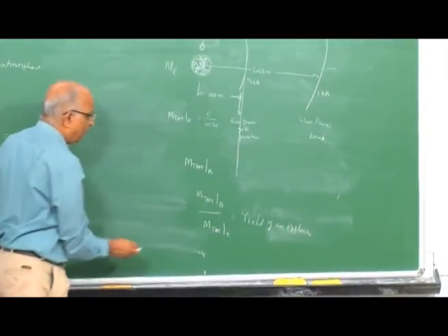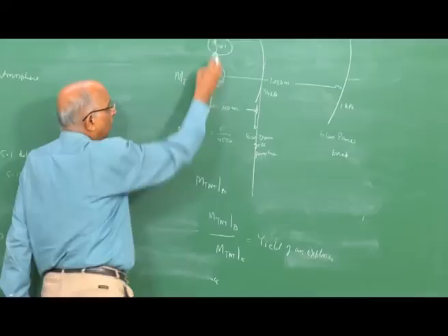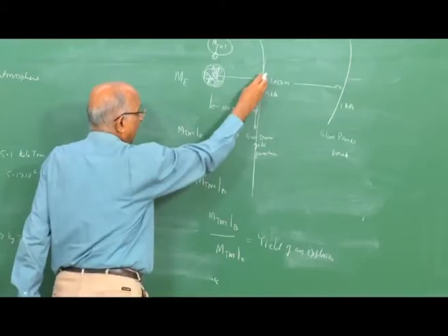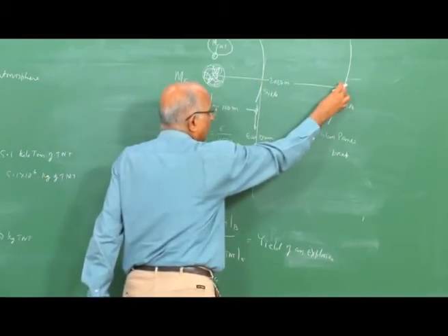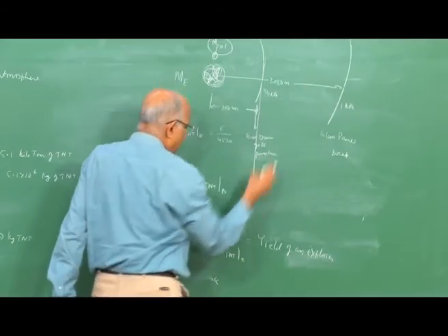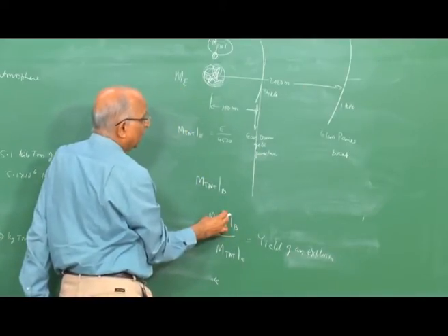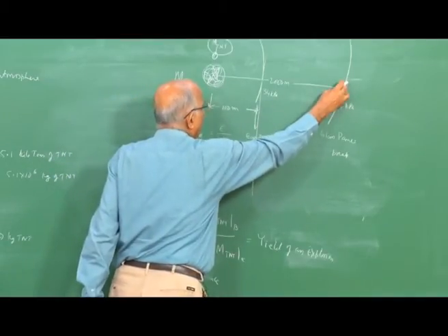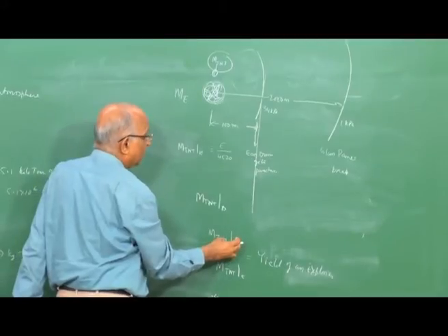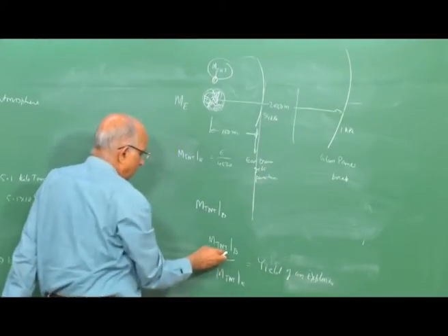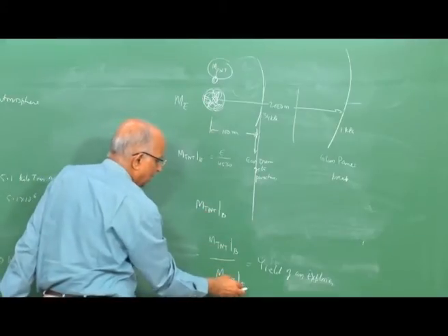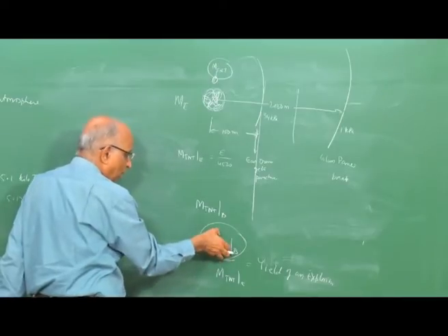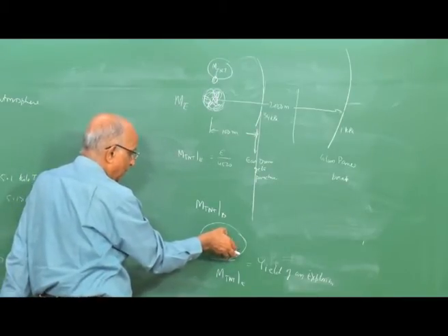Why should this and this be different? Well, in this all the energy gets into the blast wave, that means it gives me the blast at this particular distance. If I were to calculate the blast over here, since it is non-ideal, it may not give me the same value, but since I am interested in this, I calculate this. If I am interested in overpressure, I calculate the mass of TNT based on blast for that particular type of damage, divided by the mass of TNT gives me the yield, and therefore this takes care of the actual point source and the duration of the explosion.